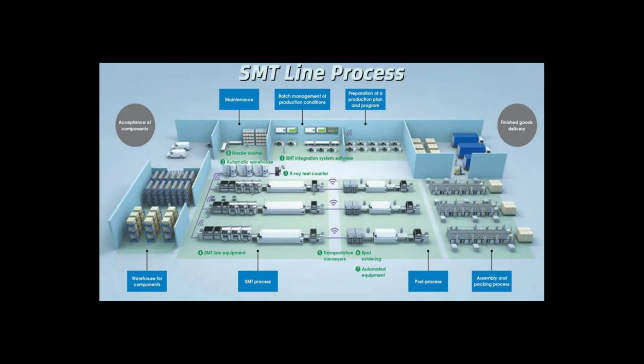This next slide really emphasizes the importance of a physical layout. Ideally, a factory floor would be laid out strategically with the equipment, the workstations, the conveyors, and other elements to improve efficiency, productivity, and safety. And as you can see in this diagram, receiving starts in the top left-hand corner, which is close to the stockroom, which is closest to the kitting. The kitting is next to the SMT line. Then you move over to rework, final assembly, final inspection, and to packaging and shipping.